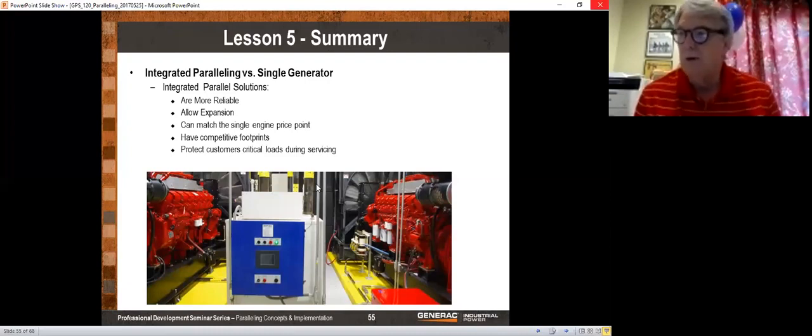You need to make sure that where you plug this thing in, we typically use cam locks, make sure that they're all color coded, and make sure that we get the right phase relationship and so on. One of the problems with that is that most people who do this have an automatic transfer switch, and when that sees a power outage, it's going to start the generator, and then the generator runs. When the power comes back, it stops the generator, and all that's automatic. Well, when you come in with a portable, now it's not going to be all automatic because you don't have that same automatic 2-wire start.